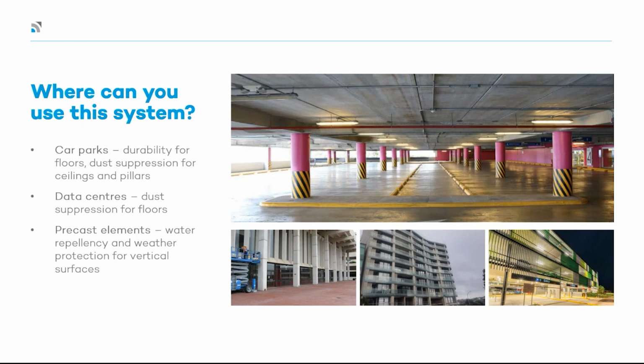Yeah, those car parks suffer from a lot of dusting issues. That's right. They get a lot of that carbonation into the concrete. So car parks are one that really get hammered, purely the fact that obviously vehicles are trafficking around, and the carbon from the exhaust, etc., is coming out, settling on the soffits or those exposed surfaces, and then starting to actually find their way into the porosities of the concrete when they're untreated, which is what's breaking it down and causing it to dust.